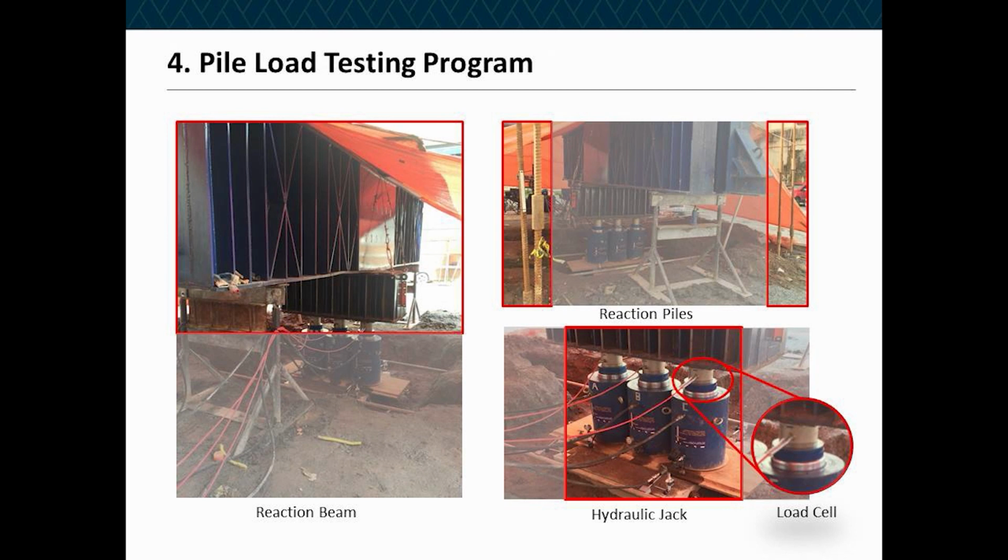The geotechnical designers, in this case ourselves, started with the design of the pile load test. So we defined the type of pile, the diameter, the length, the maximum testing loads, and also the reaction system. We followed up the execution of the test, and later interpreted the results.